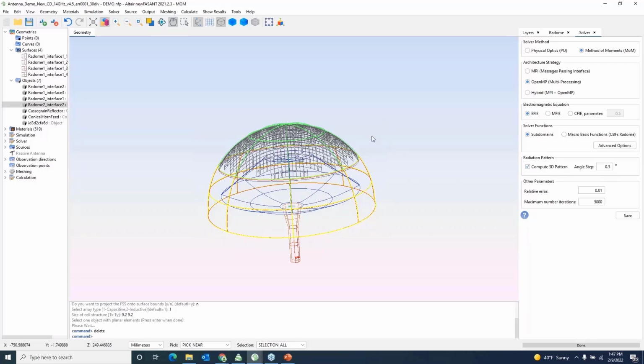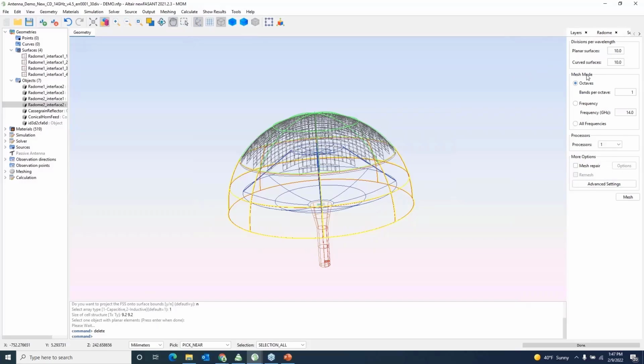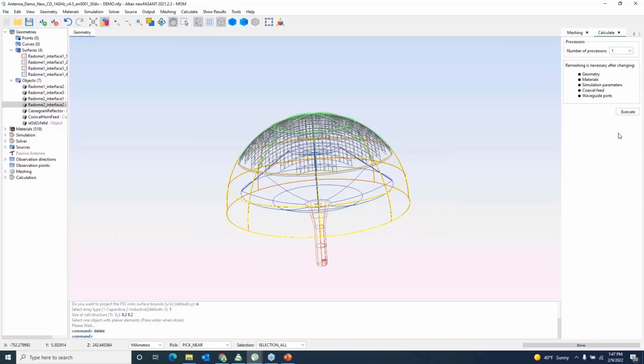degree. Once we have done this, I would like to open the results. I already solved this particular problem. Just go ahead with the mesh, the geometry, and then create the mesh and we can select all the necessary mesh elements over here, then calculate, then execute. We'll choose how many processes we are going to use and we can run the simulation. Okay, just execute this.